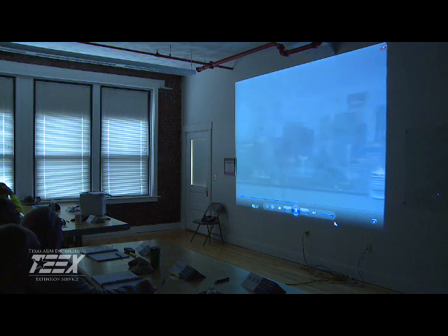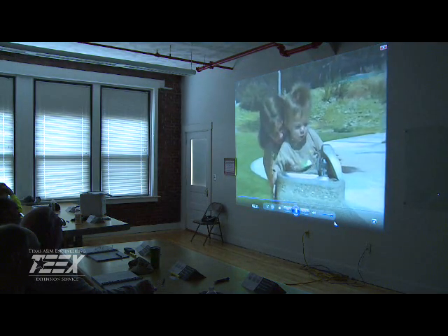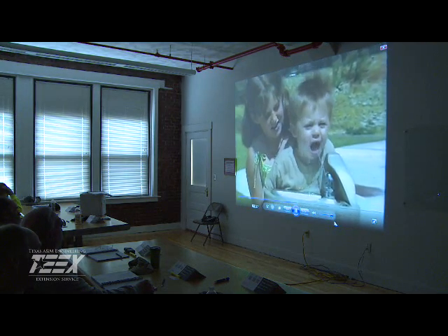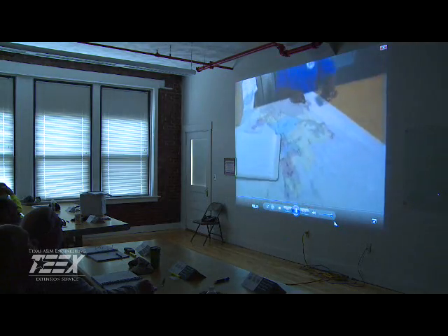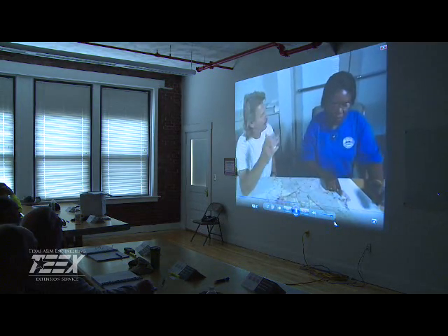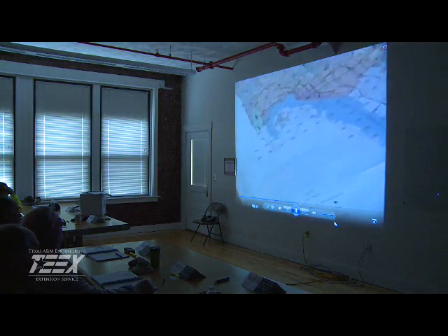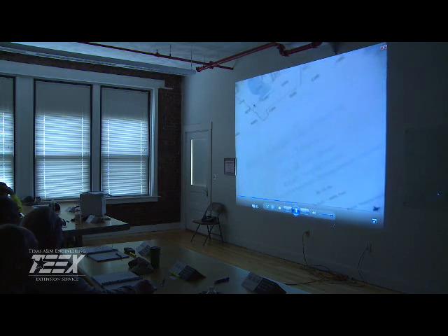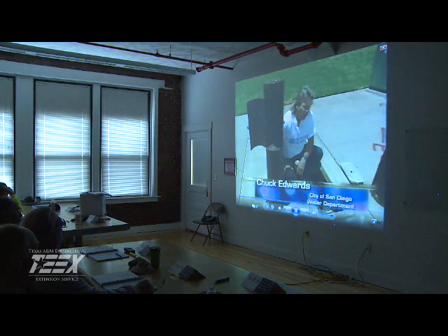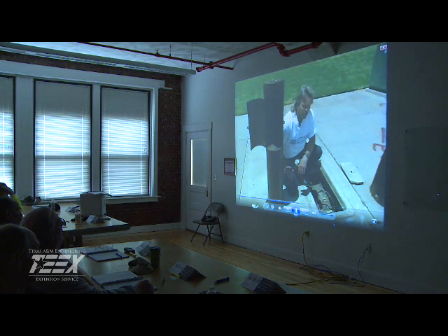So San Diego Water overhauled its sampling program and constructed dedicated sampling stations at each sampling site. They were taking water samples from inside the library. What was happening is they were getting a lot of false positives. So we decided to install sample stations right here on site. We decided to tap in before the water meter and go to the sample station.